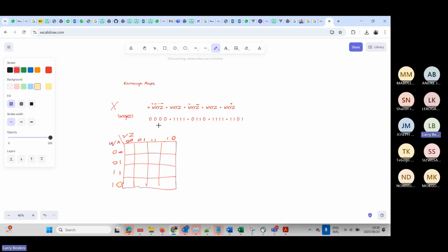Remember I told you guys about min terms. A min term means that for this combination, we will get a logic 1, right? So if we get this combination, our light will be high. Let's say you are designing the alarm system for a Ford Mustang. Then they tell you if all doors are open, let's say open is 0, for example, switch a light on. So you need that combination. Okay.